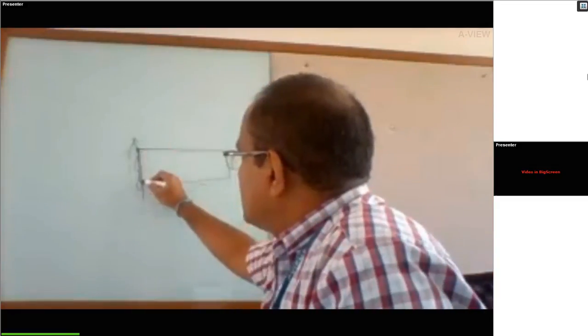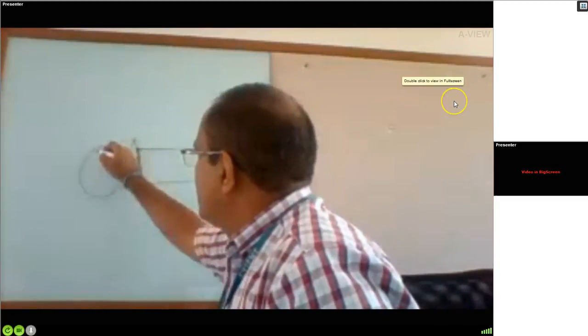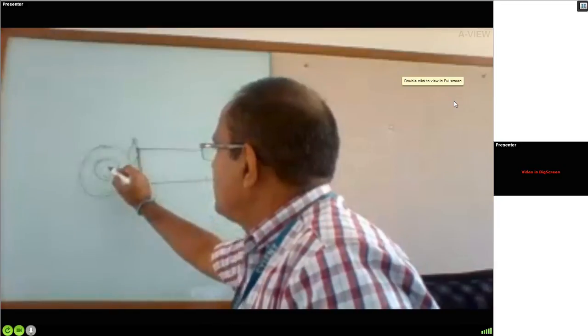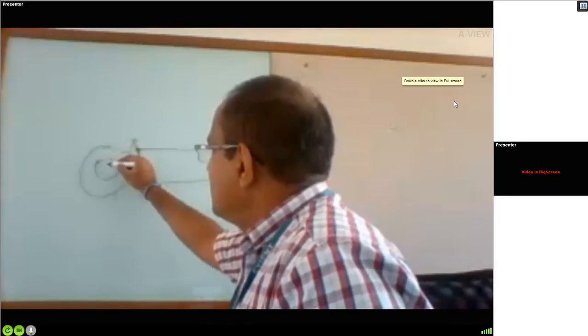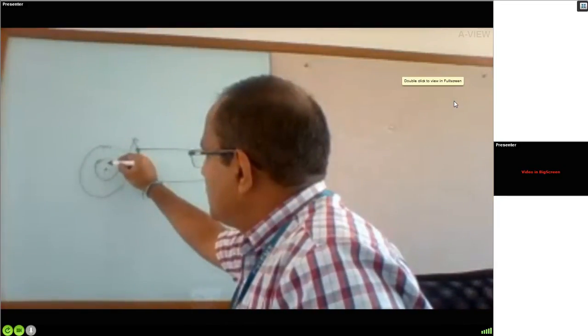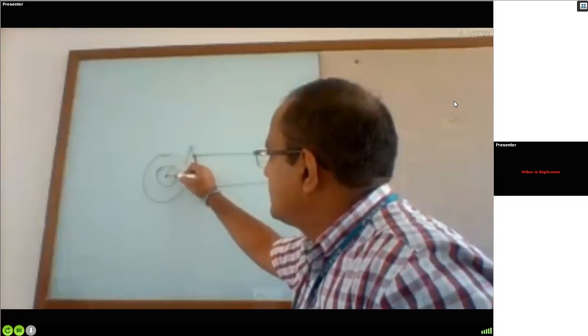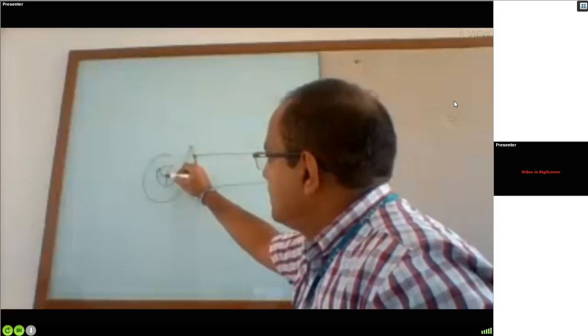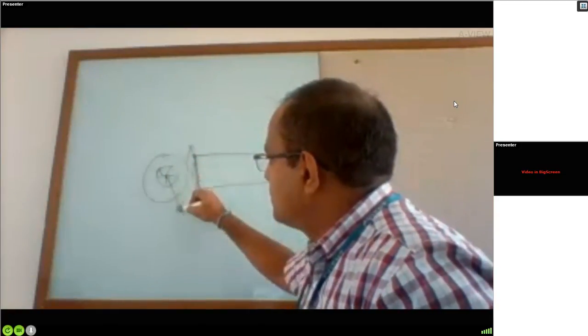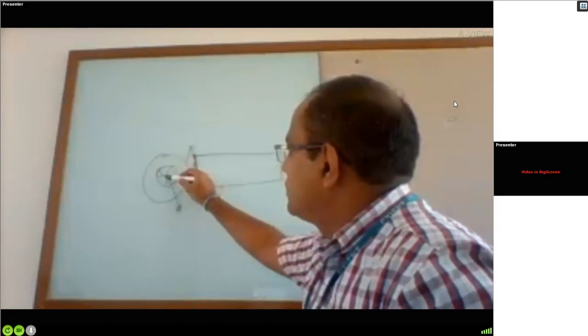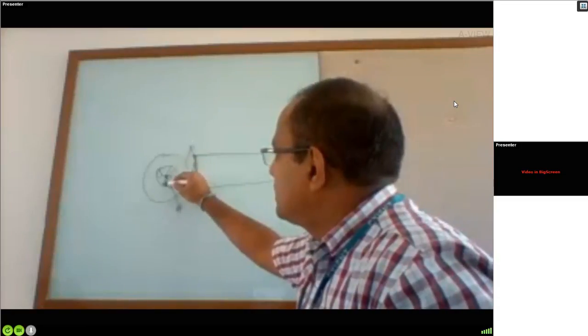Suppose here I want to constrain. Instead of considering all the nodes here, what I can do is create a mass element here, and then we will create CERIG or rigid region, and we will constrain this node. So it will impose the boundary condition on all other nodes.